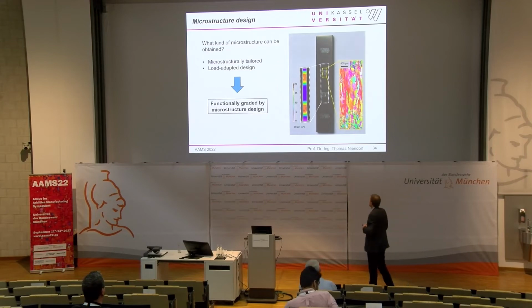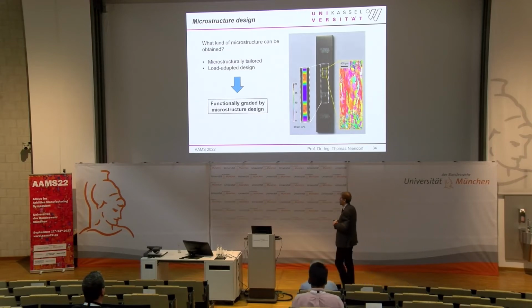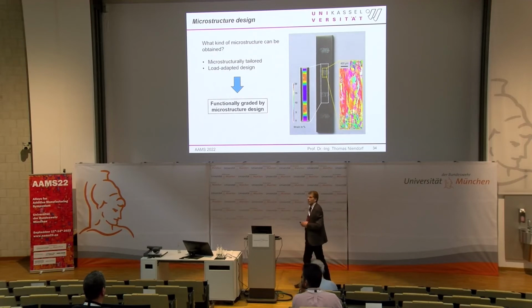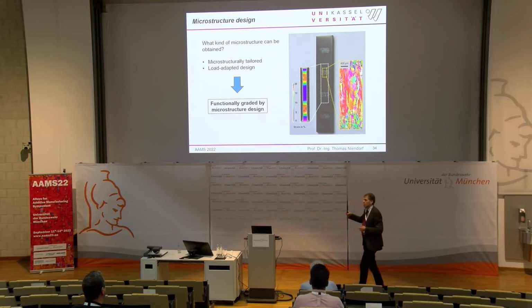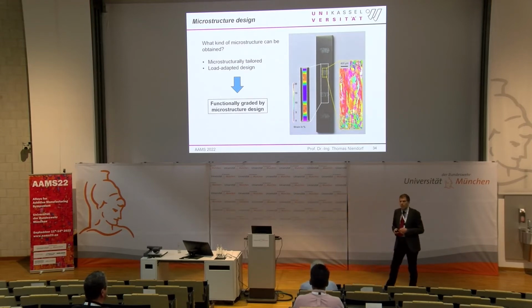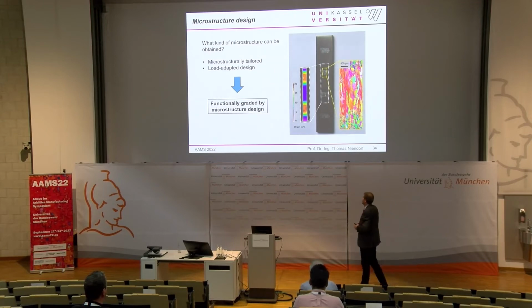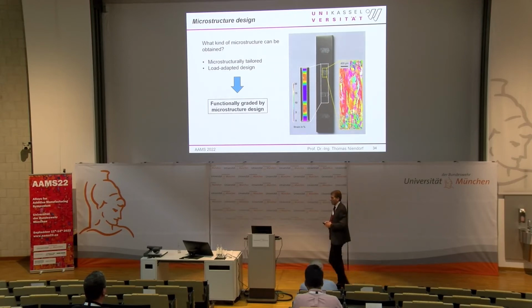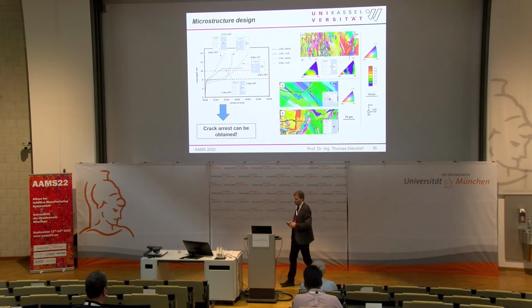So we can realize those functionally graded structures. This can be read out by eddy current technique, non-destructive, so we can imprint code in a part beneath the surface and read this out with eddy current, as I said before. So some ongoing work in that direction we do with a partner in Hanover. Very interesting now when it comes to the properties of those graded structures.